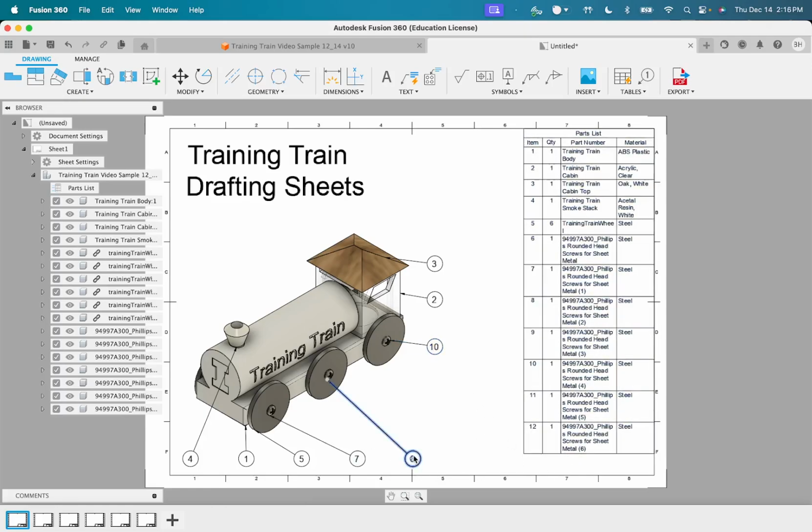But for our bubbles, we can go ahead and get rid of some of these because these all indicate specific ones. So we don't need to have the 8 because that's replicating what we already did with 7. So we'll get rid of the 8 and 10. And then you can always drag around your bubbles to make them more apparent what you're specifically pointing at and just to not cross lines or anything. So it's better to make them more apparent and not cross points. So I'm just going to make them more explicit, especially with the body itself.